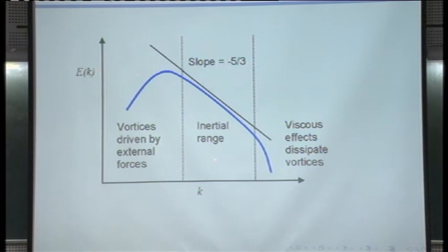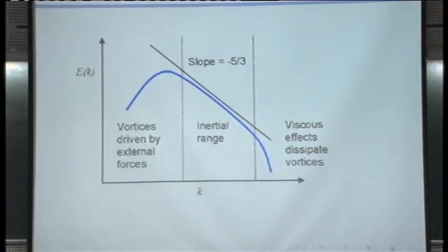So if you plot it in logarithmic scale, that's the logarithm of the energy, then the slope is minus 5/3. And this happens, and it is surprisingly precise. If you ever simulate a turbulent incompressible flow, if you have a good code, of course, you will observe that slope. Of course, not exactly. This is an idealization. You will observe something with fluctuations like that. It's not a perfect line. I'll show an example, I guess, where you will see that spectrum.